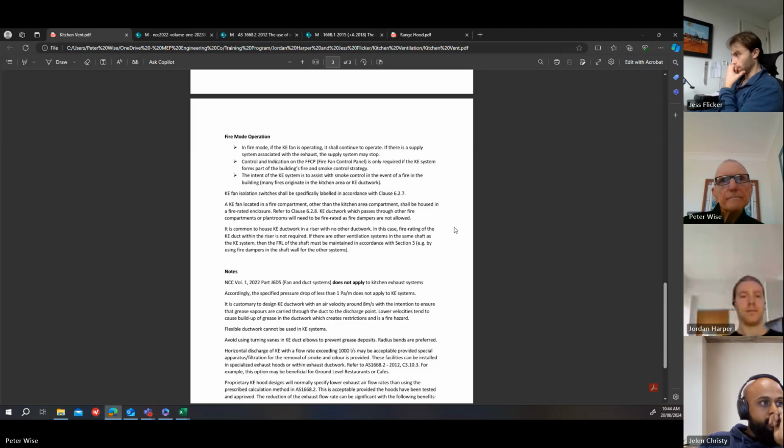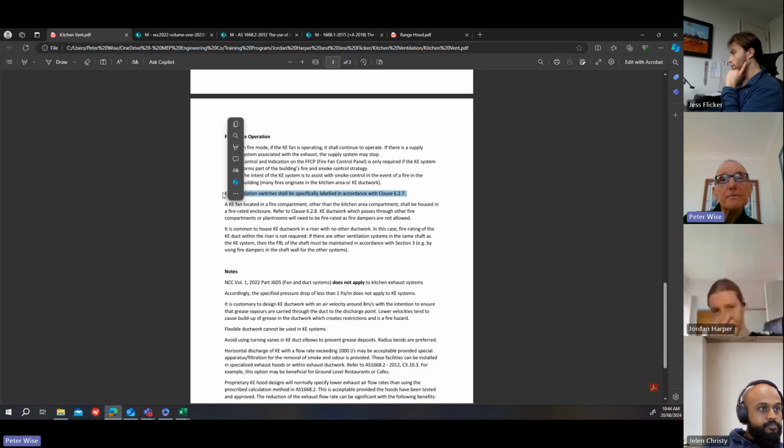Does that answer your question? Yeah. Okay. There's just a note there that kitchen exhaust fan isolation switches have labelling requirements. That's in 1668 Part 1.